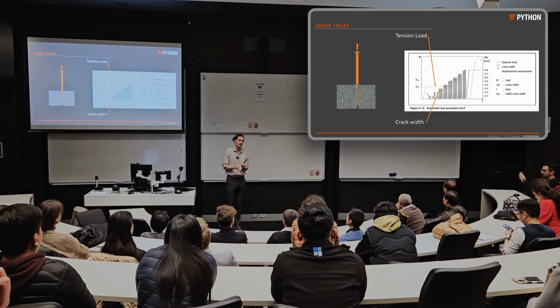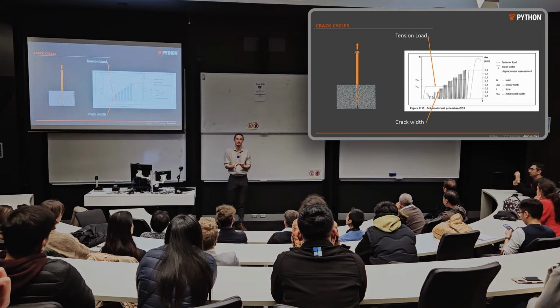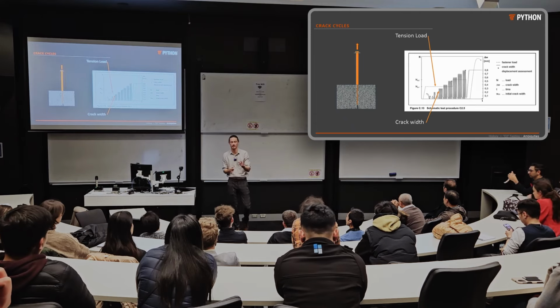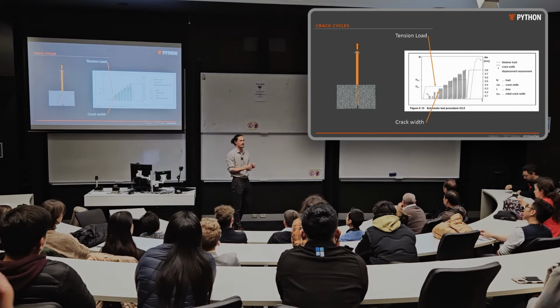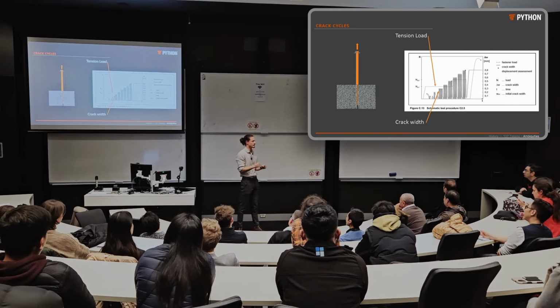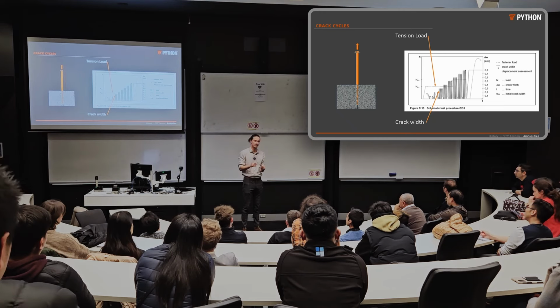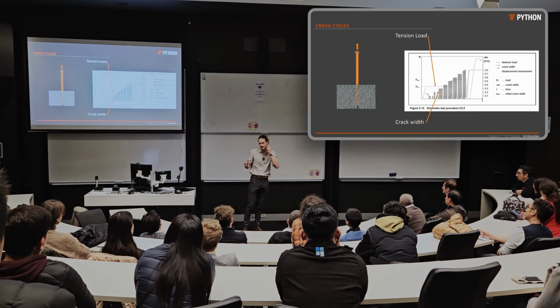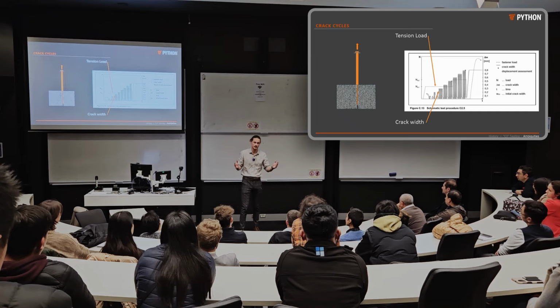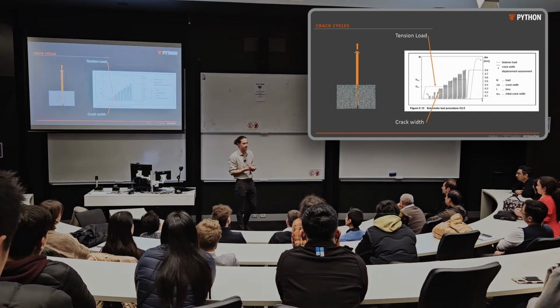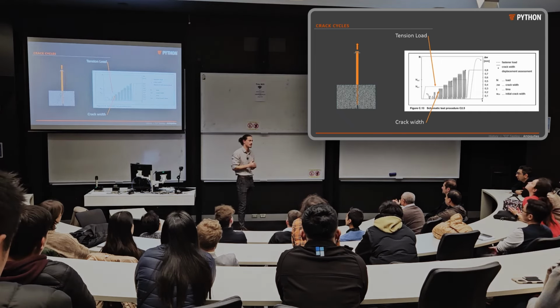This is based off a 475-year return period earthquake in LA, specifically a 90th percentile 475-year earthquake in LA. There is no method for us to scale that, or for you to scale that in design, to any other return period of earthquake. Now, this arguably is less of a problem if you're looking at shorter design lives, because your capacity is conservative. You know it's conservative. That's fine. You have that in your mind in design.